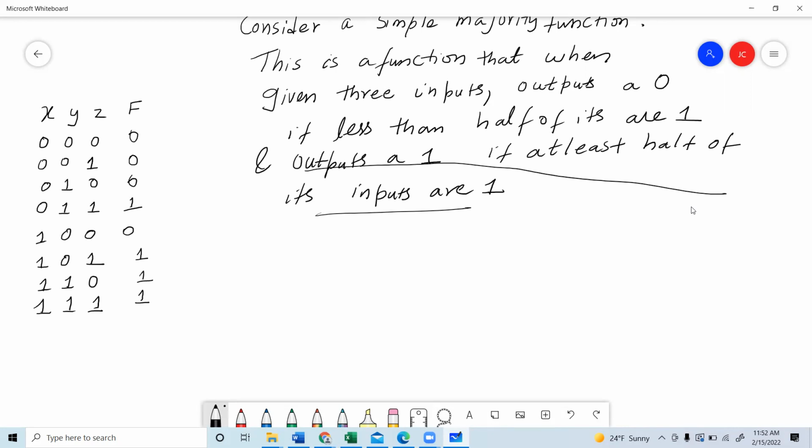Now we can write the sum of product form. So we are looking at the minterms here, M0 and so on. Each row in the truth table is called a minterm, and a minterm is the combination of inputs using AND gates. Basically, we are ANDing all the inputs, right? So f will be, we have to look at M3 because it produces output 1.